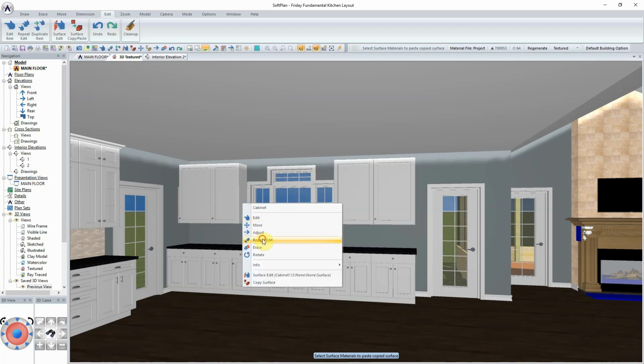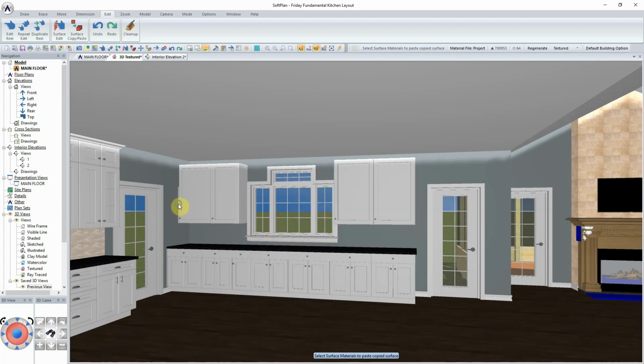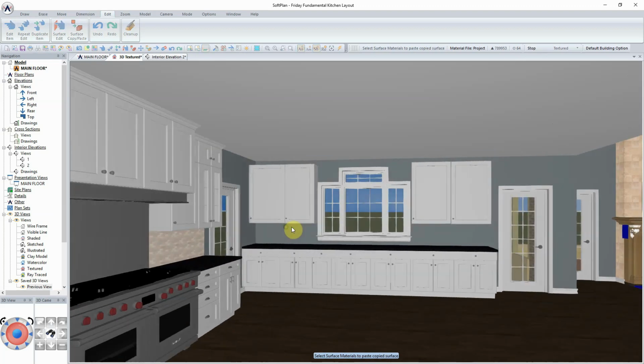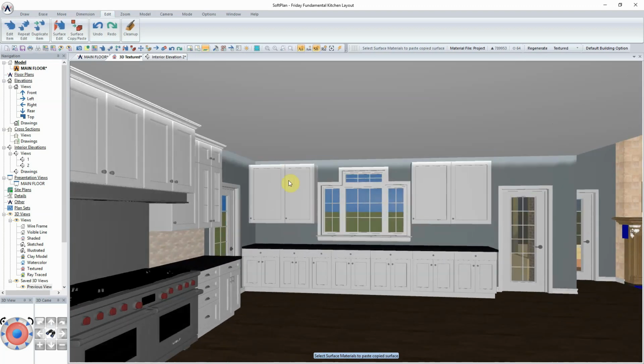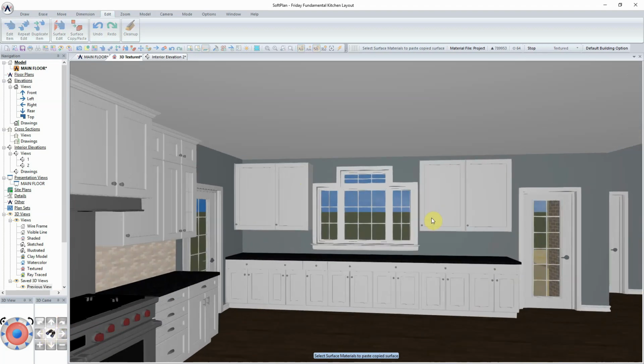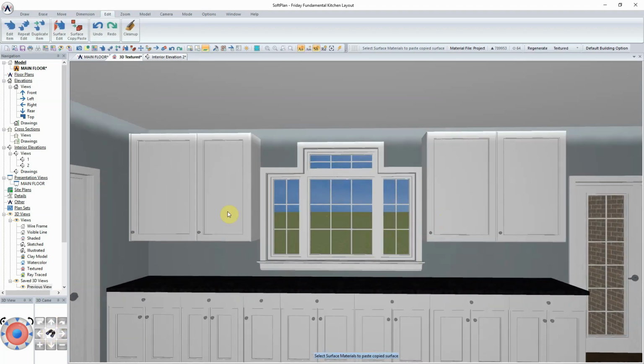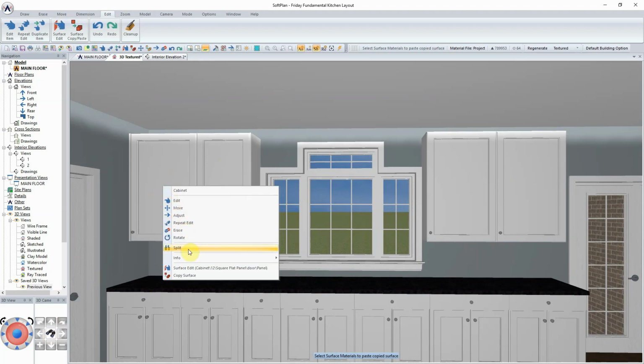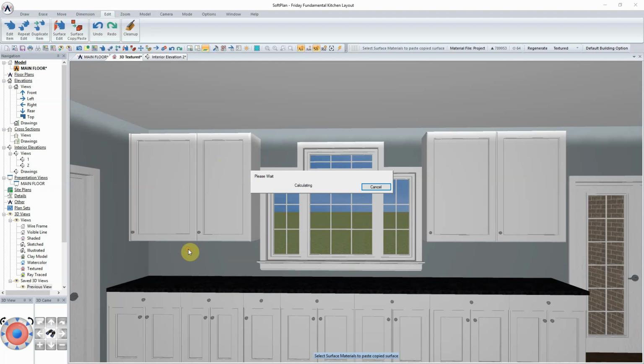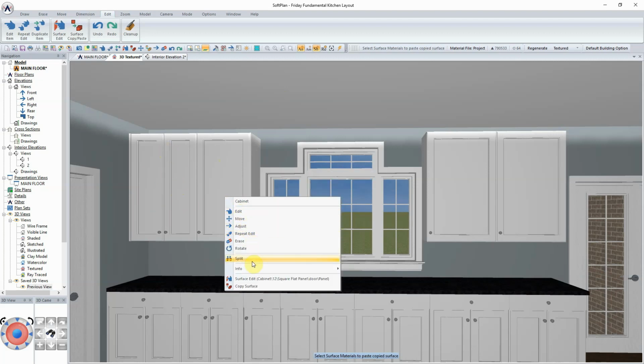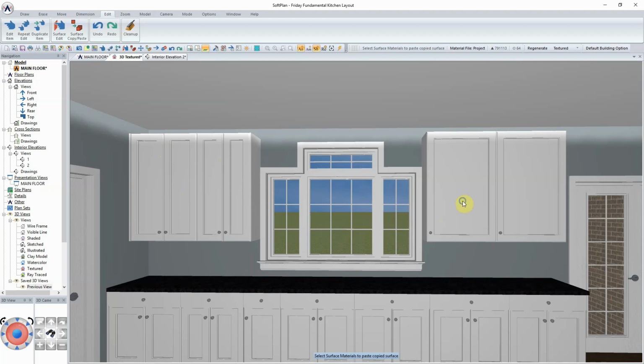And also, don't forget, we've actually gone in, and you'll see that there's possibly some fillers that have been put in there. One of the other things that I'll use a lot of as I'm taking a look at this is it placed in obviously very large doors. And so if I were to right click on this, I can select the option called split. And what it will do is it will split these cabinets into two doors rather than one door fitting within the box. And so I'm just going across and doing that for all of these.